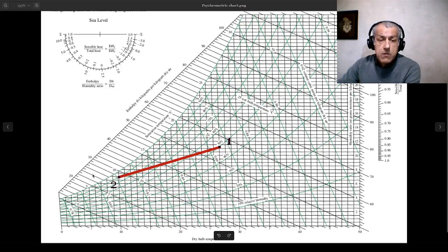We could also read values for enthalpies from these two lines and from this point and this point. So if we just use this psychrometric chart, we could place different points of our problem or our different problems on this chart, draw our processes, and also calculate enthalpies and specific humidities for different points and bypass, in fact, those calculations.